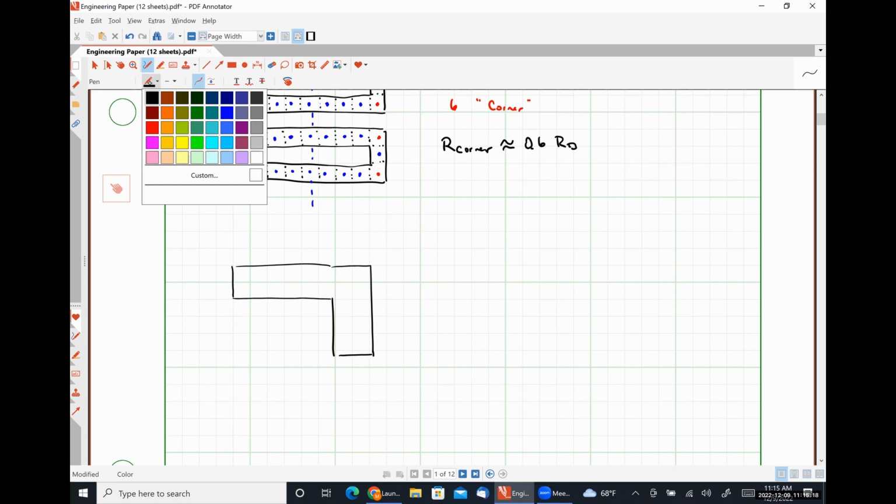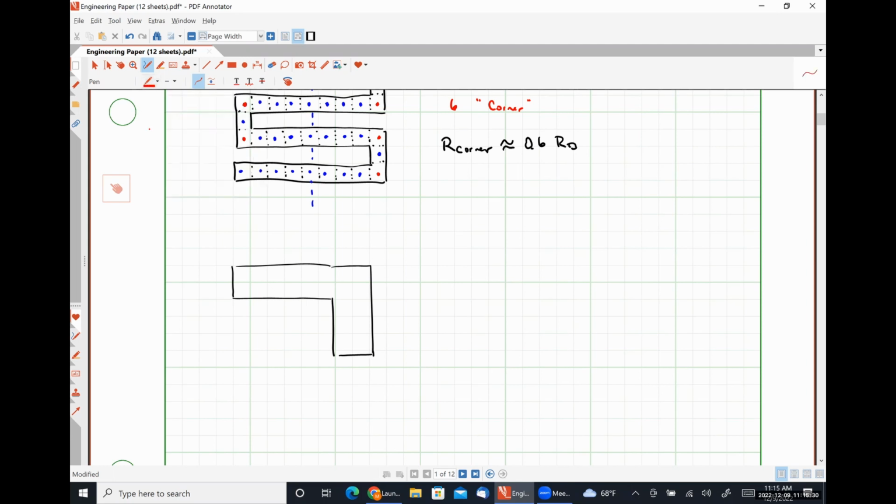So if we have a DC current flowing through a wire, we would normally expect that the current distribution is uniform along that section of wire, okay? Well, when we bend it, what we're going to see is we have a uniform current density, and then it gets concentrated here, and it doesn't reach that outside corner.